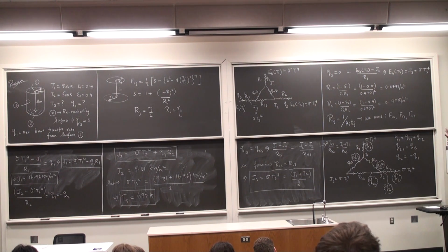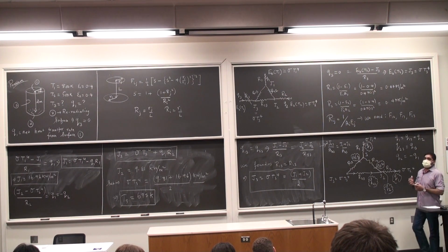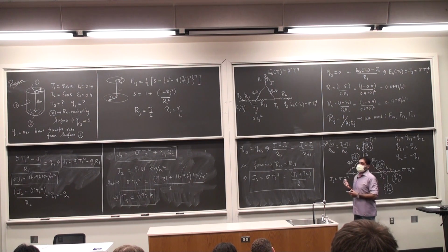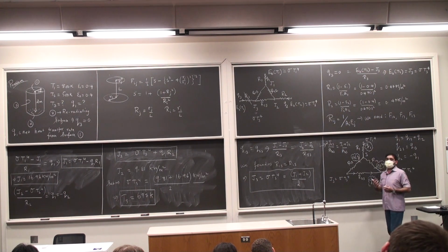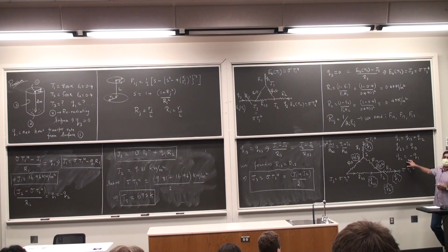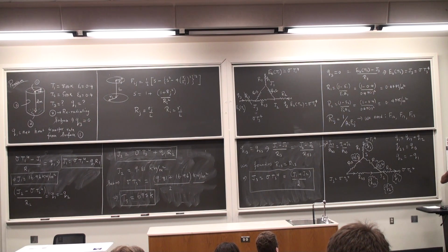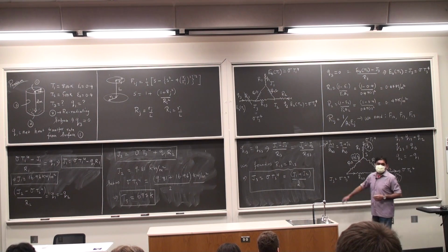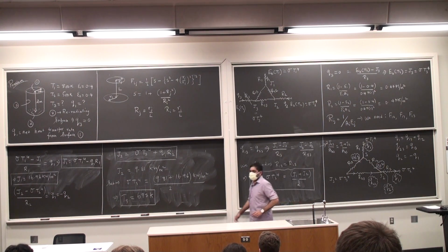Once you do that, you go through all of these characters here, the surface resistances, which are R1, R2 and R3. Then the geometric resistances, which are the Rij's, R12, R23 and R13. Once you do all those calculations, it is just an application of Kirchhoff's current laws. Pure manipulation, that's all it is. Okay? Alright. Last questions on radiation. That ship is sailing soon.